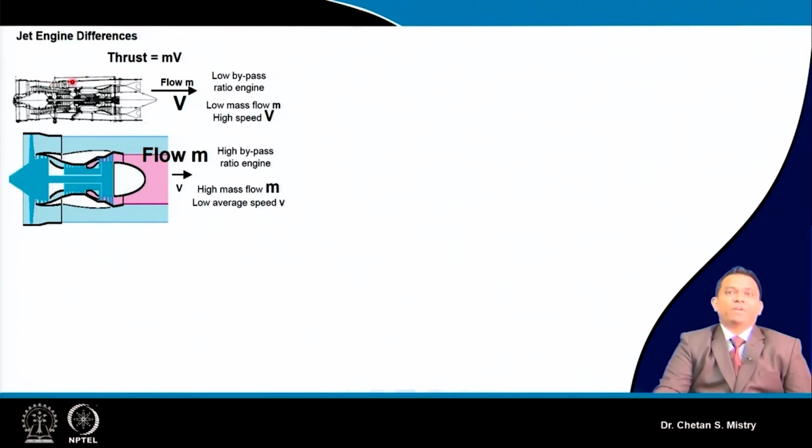Since the dimensions of a turbojet engine are fixed, increasing the mass flow rate is a constraint. The next option was to increase the exhaust velocity. But for that, the turbine entry temperature needs to be higher, and that's where the constraint comes in with the type of material we are using for the turbine.